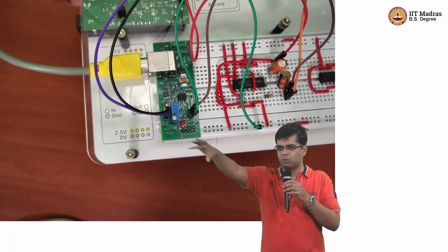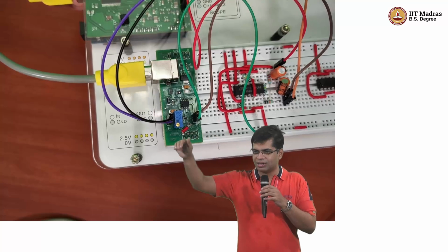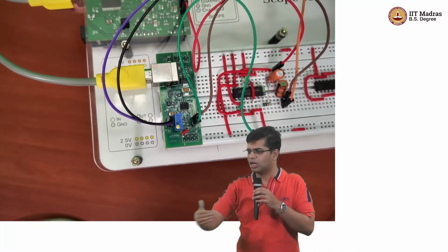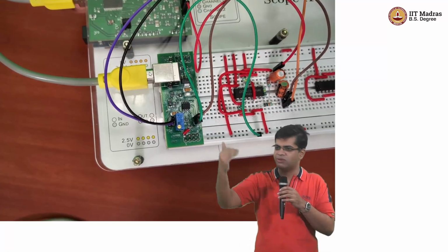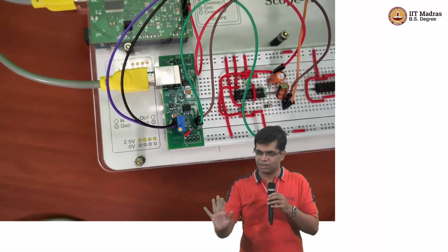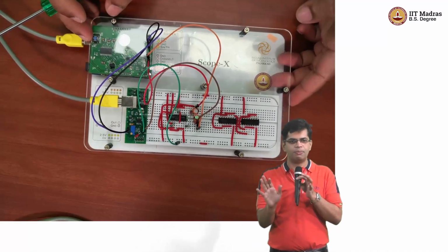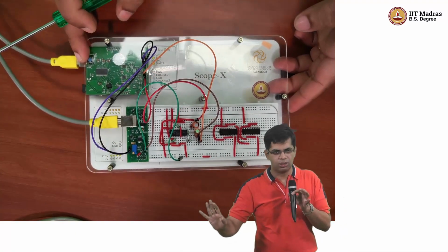So if I have a textbook op-amp circuit, anything that is at 0 will go to the 2.5 line. Anything at minus 15 will go to the ground line, and anything at plus 15 will go to the 5-volt line. That's essentially what you have to do. As long as you use a rail-to-rail op-amp, you can do all the circuits that you normally learn using this.